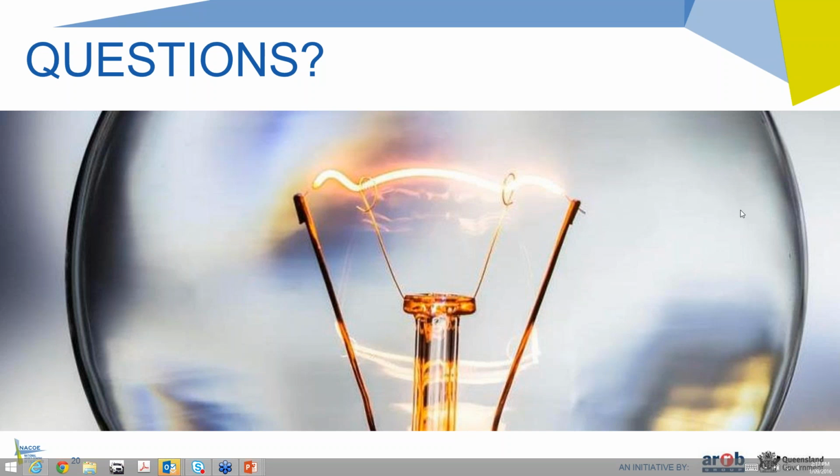We also revisited the presumptive design moduli that we were using, and based on more recent mixes we're able to increase the moduli, which resulted directly in a reduction in thickness. So it wasn't really one individual thing, it was a whole lot of little things that really added up to the difference that you can see from that chart between the 2009 and 2013 thicknesses.